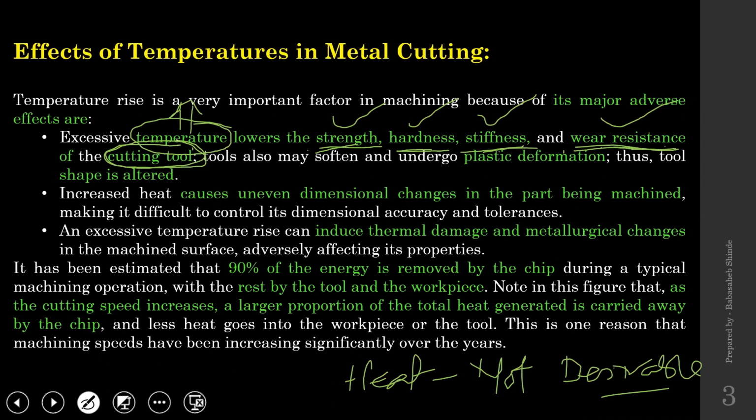Additionally, the thermal softening of the cutting tool may happen, and in the worst scenario, that may result in plastic deformation also. So the cutting tool might deform plastically because of the extent of the heat generation. That is going to be the worst scenario. You won't observe it regularly, but that also could happen. So these are the various effects on the cutting tool. Next,